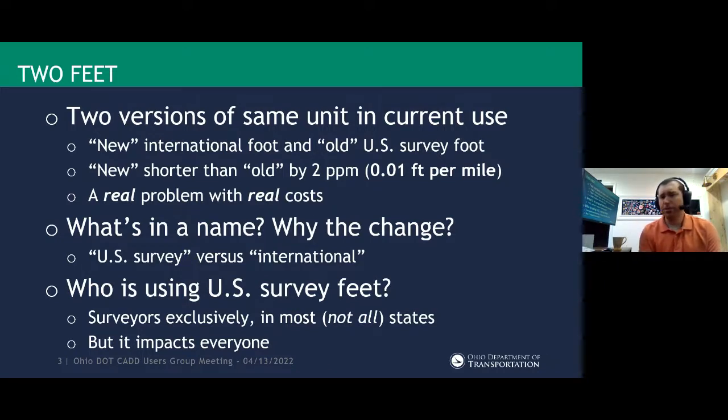So who's using the U.S. survey foot? Really, it's only surveyors, and not all states have the survey foot legislated. Ohio is one of those that actually has the U.S. survey foot legislated, so that'll be another change that's going to happen really soon as well.